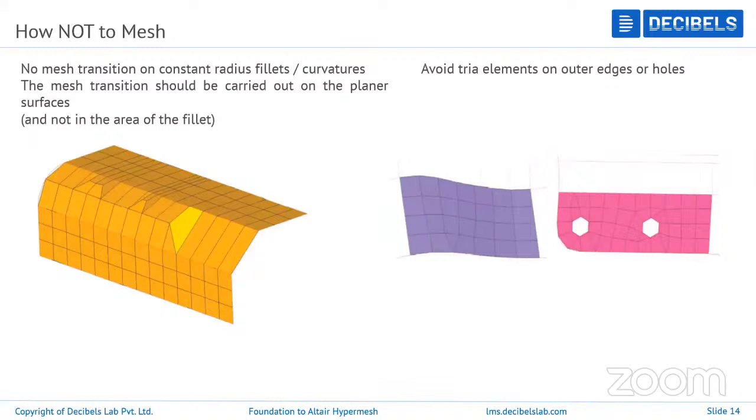In most cases, for any automotive part or assembly, wherever you go, we majorly use 2D meshing only. For casting components, when the thickness is not comparable with the other two directions, only then do we go with 3D meshing. Most of the time, say for example with 100 components, for at least 60 to 70 components we go with 2D meshing only. So 2D meshing is very important, and the topics I have discussed here are the important checks to be done when doing the 2D meshing.